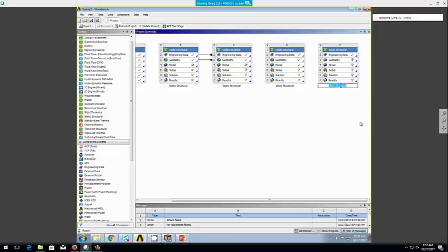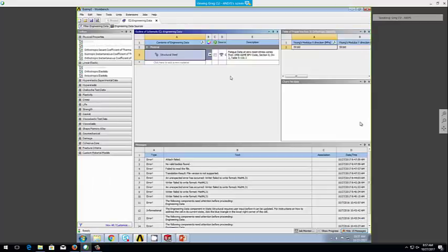Reference temperature, I can change these sorts of things. What I'm predominantly interested in for this motor mount is changing the material. I want to change the material to something really great. We'll do it as titanium alloy because it's exotic. So now this is going to be titanium alloy. If I had more than one geometry in here, I could specify each body could have a different type of material.